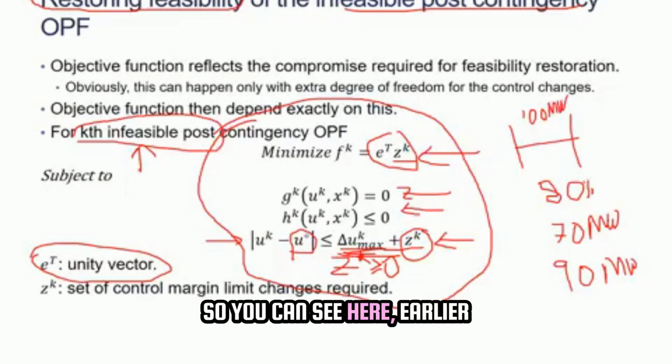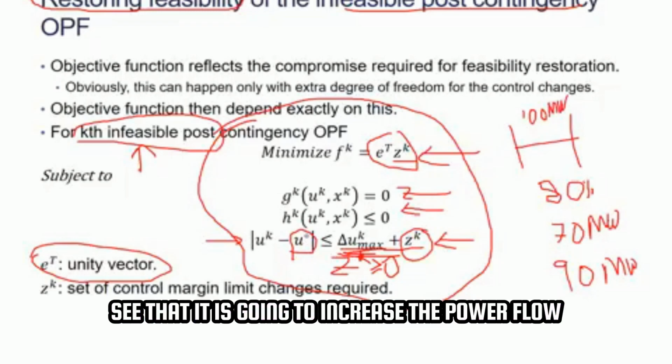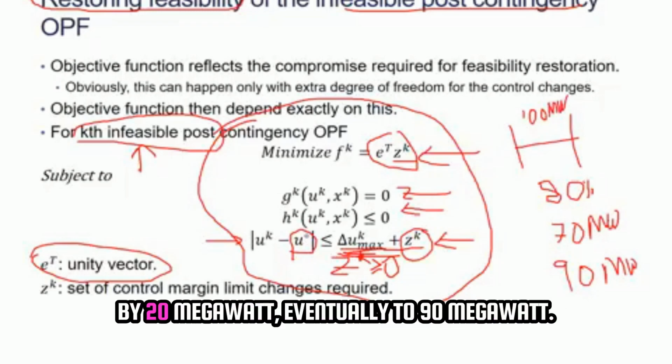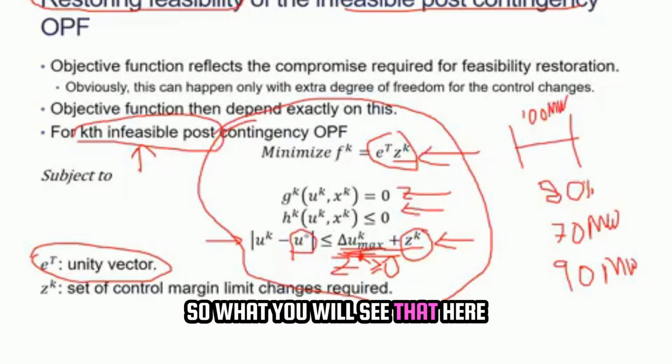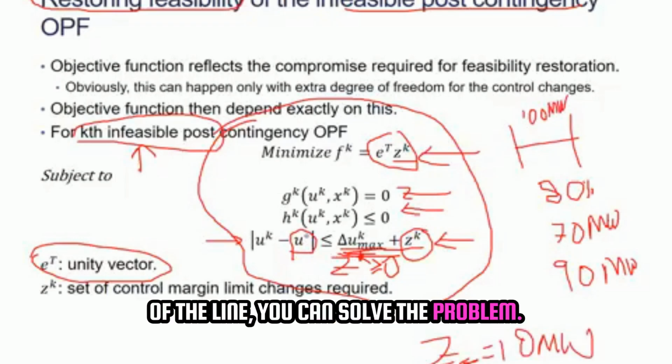So you can see here, earlier it was 70, it was fine, everything was fine, but because of this kth infeasible contingency, we see that it is going to increase the power flow by 20 megawatt, eventually to 90 megawatt. So for this kth contingency, Zk will come out to be 10, because by increasing the capacity of the line by 10 megawatt, you can solve the problem.